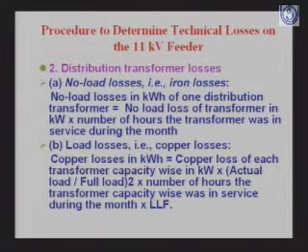Long back when the Eastern Grid was running at 50.5 Hertz frequency, then whatever nameplate rating is there would not remain constant, that would get changed. The same is vice versa when the frequency is maintained at 49.5 Hertz. It happens in certain pockets where you will have low frequency at certain times because the demand on the grid is very high. But for all practical purposes, we take the no load losses as mentioned in the nameplate of the transformer.